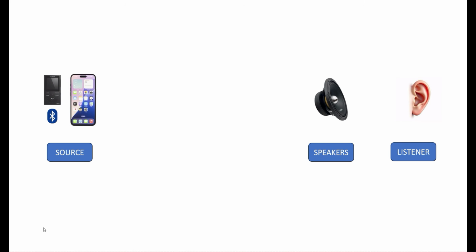So let's have a look at another type of setup. This time, let's look at a DSP amp combo, where we have a DSP like a Helix V8 or something like that, that has a built-in amplifier. It's a little bit like the head unit example, but in this case, the line signal from the source is sent to the DSP, and the DSP manipulates that line signal by adding timing or EQ filters and cuts and boosts and whatever else, and that signal is then amplified by the DSP. And all that's happening in the DSP at once.